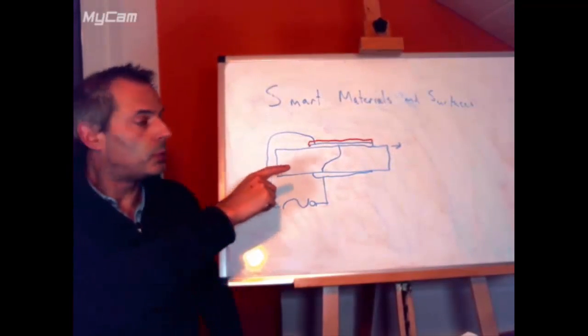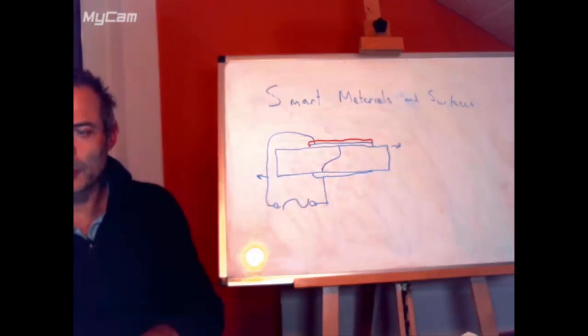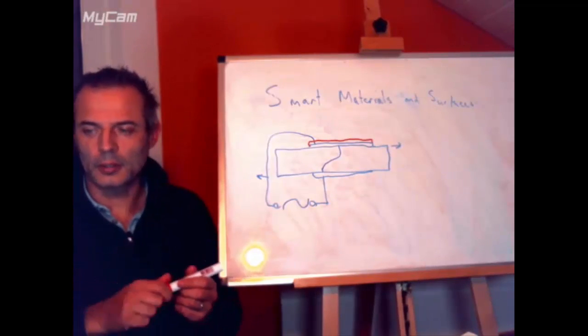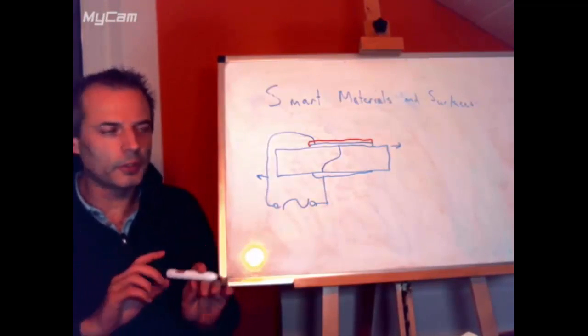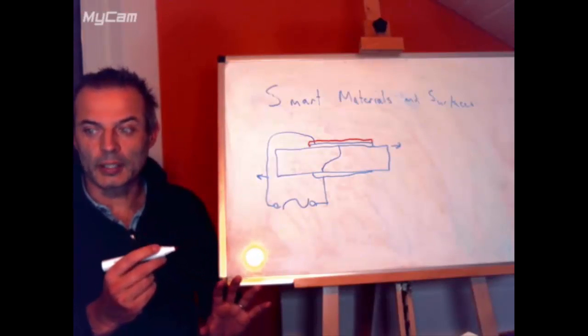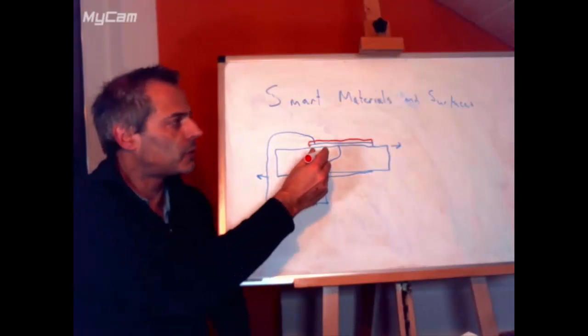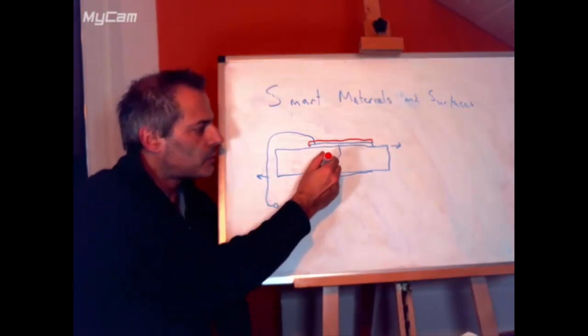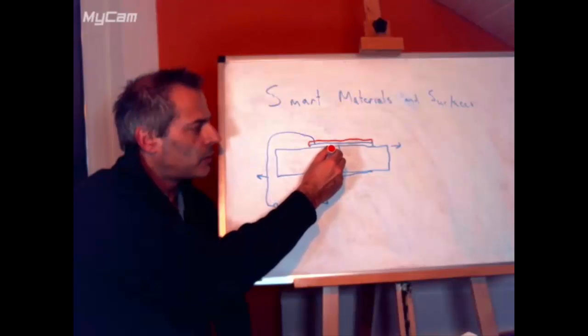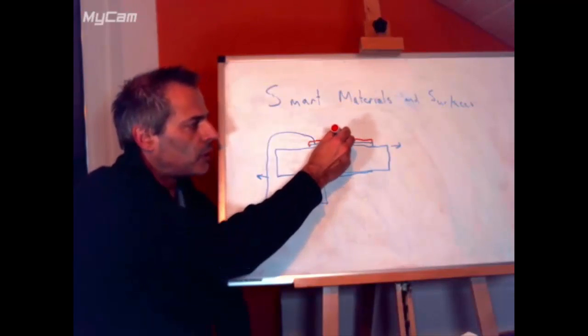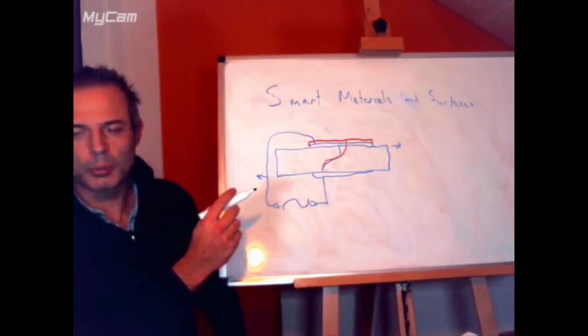Okay, so now we put an extra layer of something else on the top of our crystal, and it behaves to a first approximation just like extra quartz. So we've made our piezoelectric material a little bit thicker. It shouldn't have increased in amplitude.